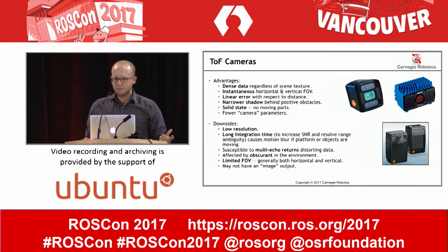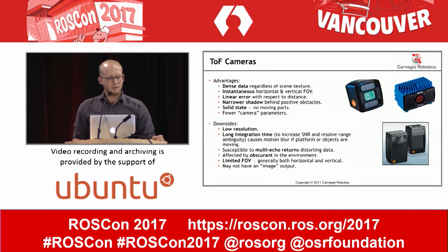These are generally much denser than 3D lasers, but have higher power for the range that they're perceiving due to the higher density and the way that they're electrically built. They have generally intensity outputs. They almost act like a camera, and they bring their own illumination with their IR emissions, but they don't really have camera parameters that you can tune, and this is both an advantage and a disadvantage depending on the environment